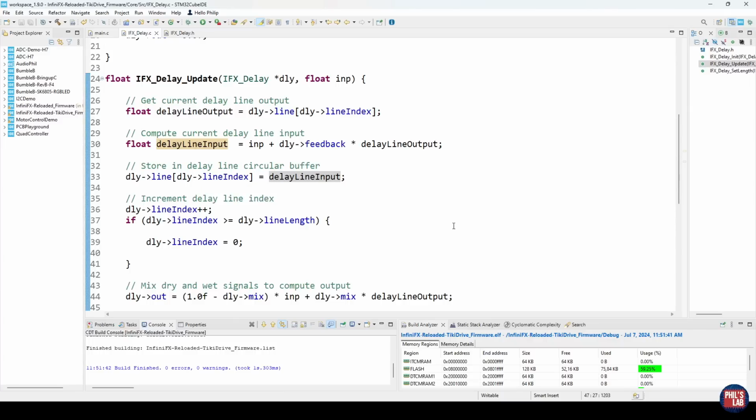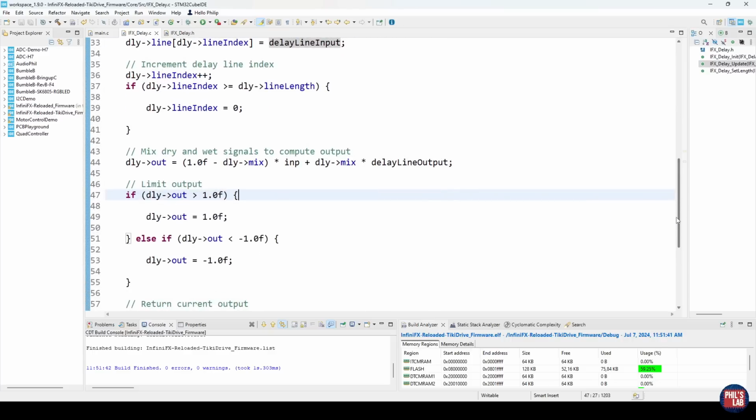If you want to do an analog delay, I might put a variable low-pass filter in the feedback path. So this serves as a great starting point to implement various different delay effects and to play around with different delay effects, but these are the pure essentials. Before we compile this code and upload this to the board, let's just check out how we're changing the parameters and how this effect is called.